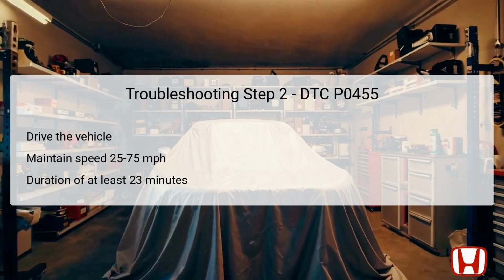The driving cycle helps develop stable temperature and pressure conditions necessary for accurate leak detection. It is crucial to comply with these guidelines to prevent erroneous readings, which could lead to unnecessary repairs or misdiagnosis. Once completed, the vehicle should be allowed to rest before checking for any DTCs stored by the PCM.